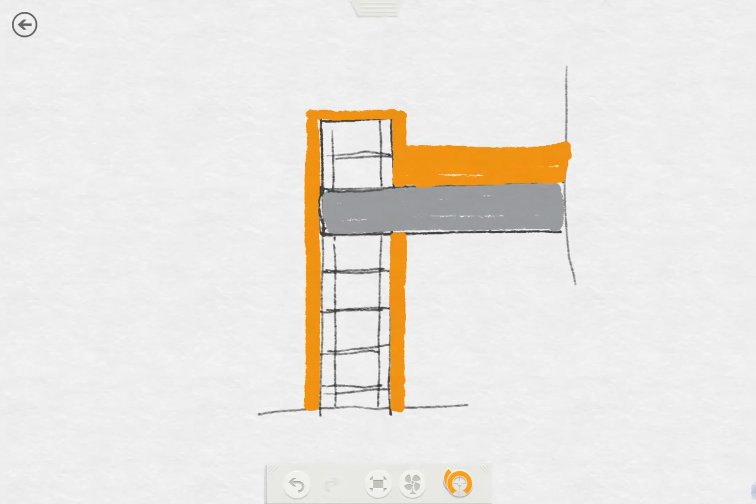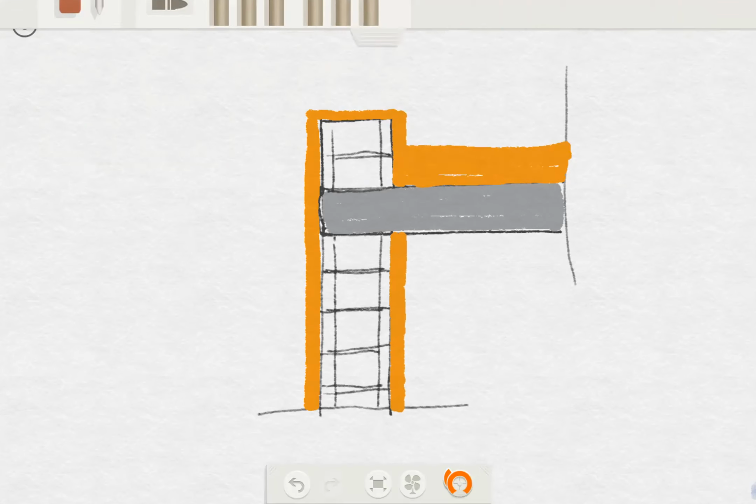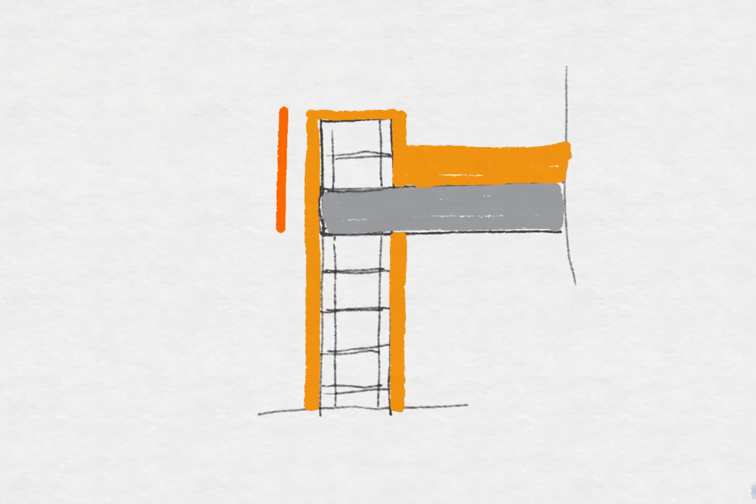The problem is that we have to protect the thermal insulation material because we cannot have thermal insulation indoors and outdoors. So we have to protect this material. How can we do that? The external finish can be, let's say, brick. As it was stated in the classwork, we need brick here.